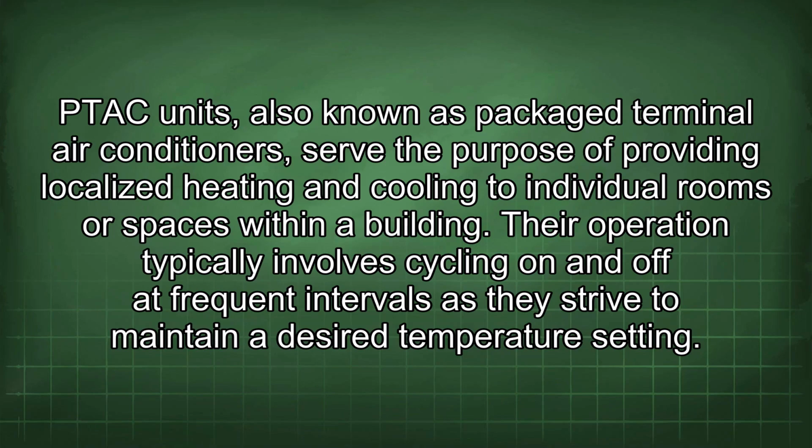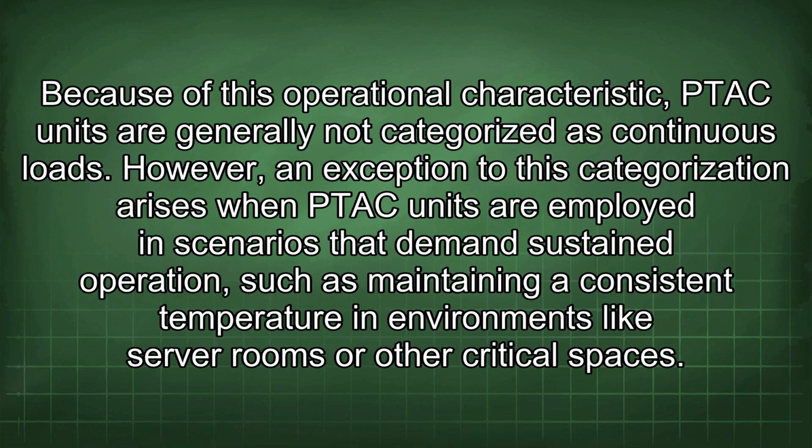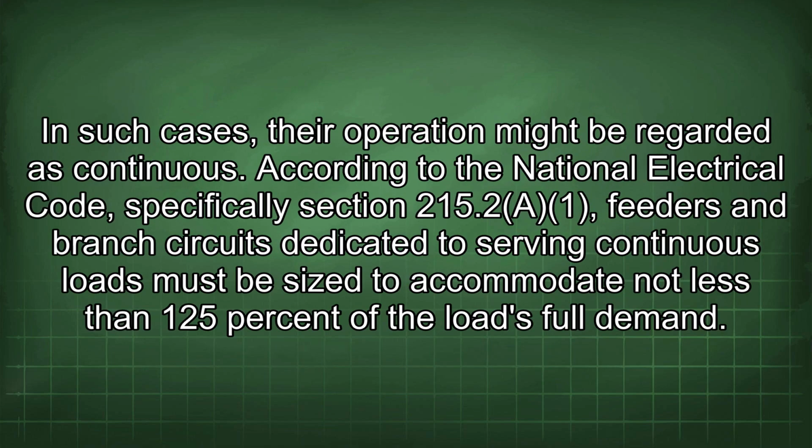TAC units, also known as packaged terminal air conditioners, serve the purpose of providing localized heating and cooling to individual rooms or spaces within a building. Their operation typically involves cycling on and off at frequent intervals as they strive to maintain the desired temperature setting. Because of this operational characteristic, TAC units are generally not categorized as continuous loads. However, an exception to this categorization arises when TAC units are employed in scenarios that demand sustained operation, such as maintaining a consistent temperature in environments like server rooms or other critical spaces. In such cases, their operation might be regarded as continuous.